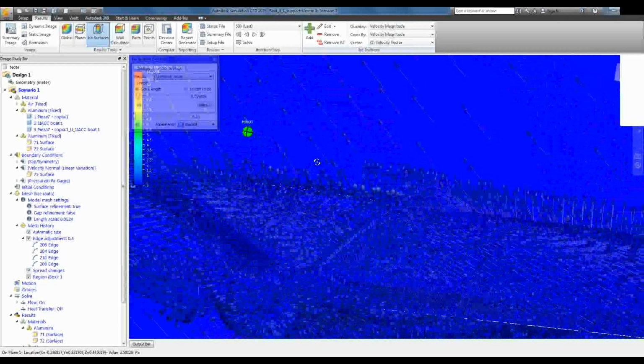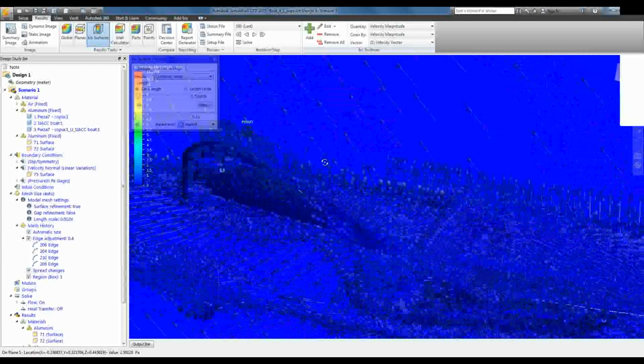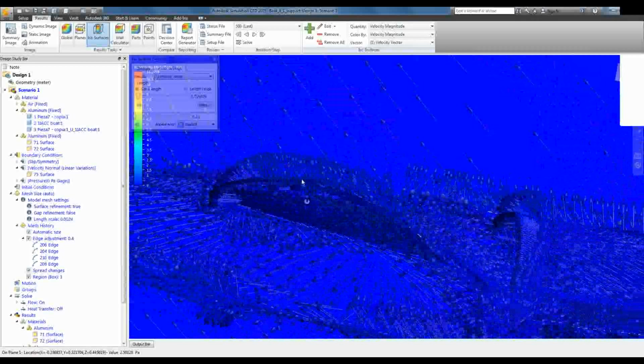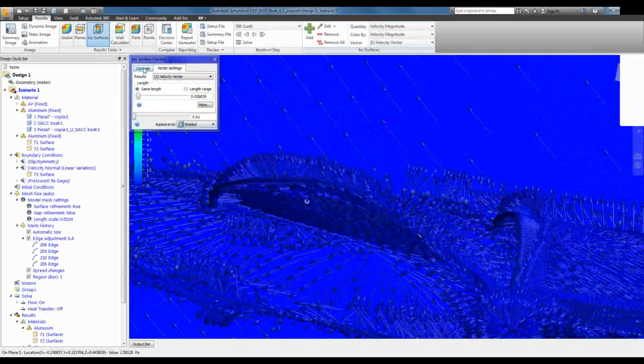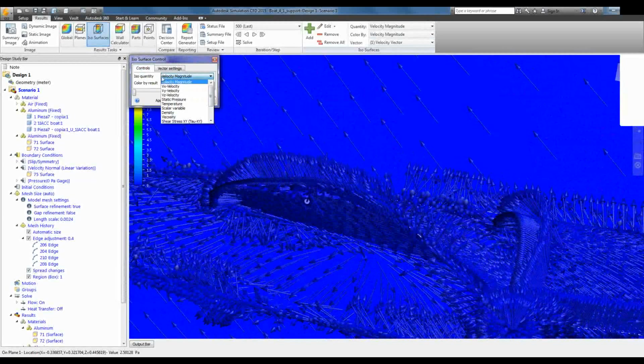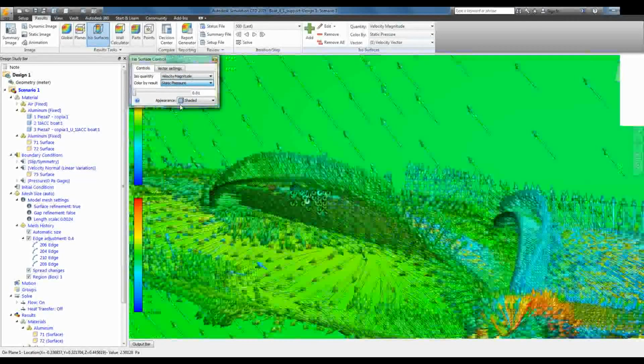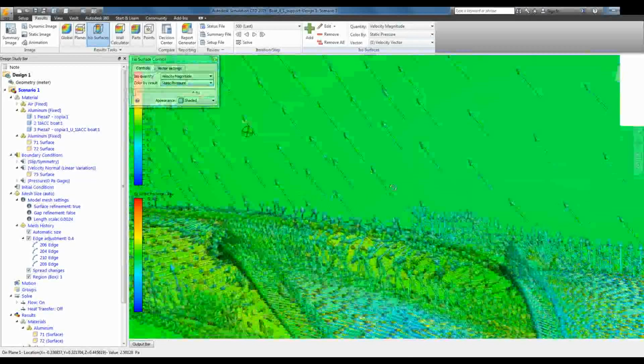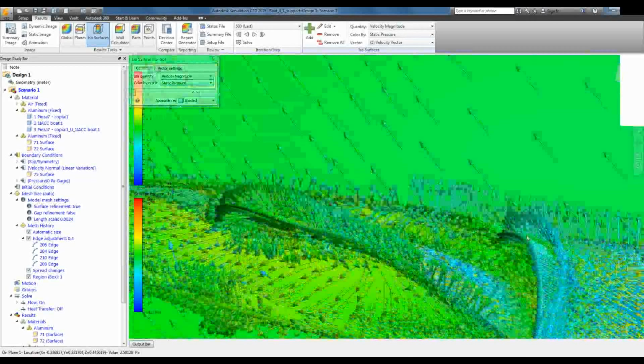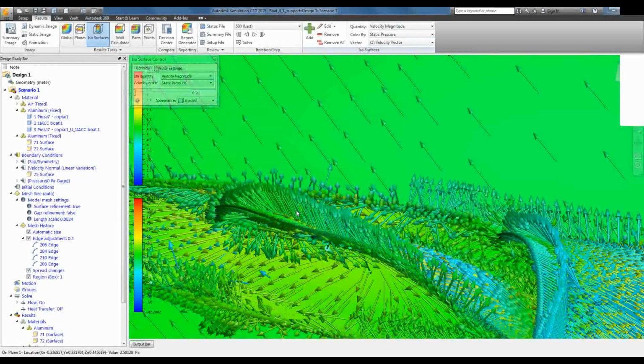Okay. So here you can actually see some of the reverse flow with the ISO surfaces, but if you switch it to pressure, you might be able to get a better idea with coloring and depth of field. Color by result. Yeah. There we go. Oh, much prettier, right? You can see here's the leech of the jib, and there's something funny going on there, and something funny going on here. Now, the flow's not perfect. Well, we have a sail blocking the flow, so you would expect some of this, and this is what sail designers would be trying to minimize to enhance their performance.